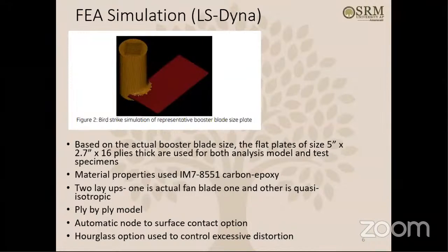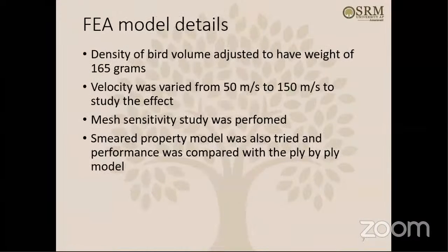Then, of course, in LS-Dyna there are a large number of options. We used the node-to-surface contact option, and the hourglass option was used to control excessive distortion. Also, the density of the bird volume was adjusted to have a weight of 165 grams.